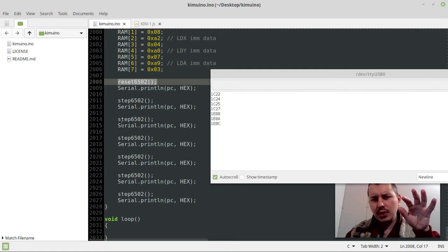I just wanted to execute a few instructions to make sure that my ROM read instructions are working properly. Since the ROM is located in program memory, we need to use this specific macro, pgm_read_byte_near, that is available for Arduino, to make sure that we retrieve the proper values and to track the program flow a little bit, before we do this in the infinite loop, which will be the case a little later on.